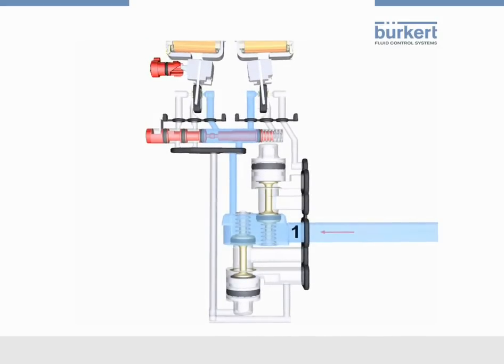Compressed air is applied to channel 1, reaches the inside of the main valve, and is depending on both seats of the servo-assisted valves. If the left servo-assisted valve is switched, the compressed air can surpass the servo-assisted seat and lifts the left piston in the pneumatic amplifier against the power of the coil. By the lifting of the piston, a connection from channel 1 to channel 2 is possible. Channel 2 is the working port where, for example, a process valve can be connected to.